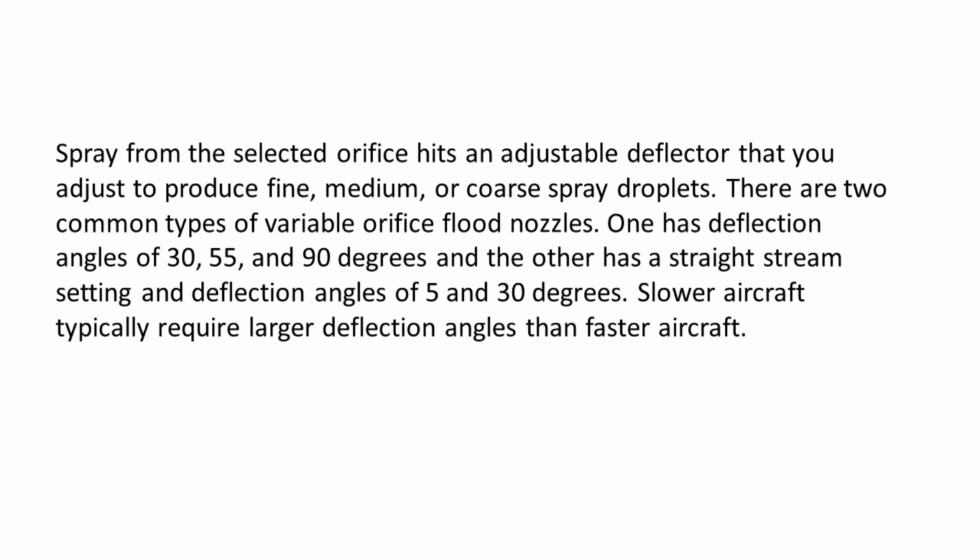There are two common types of variable orifice flood nozzles. One has deflection angles of 30, 55, and 90 degrees, and the other has a straight stream setting and deflection angles of 5 and 30 degrees. Slower aircraft typically require larger deflection angles than faster aircraft.